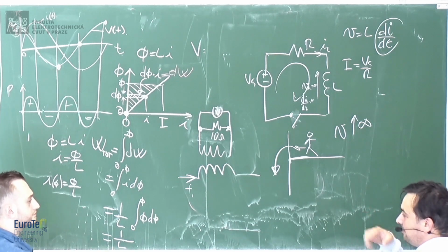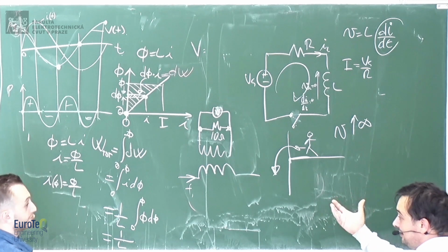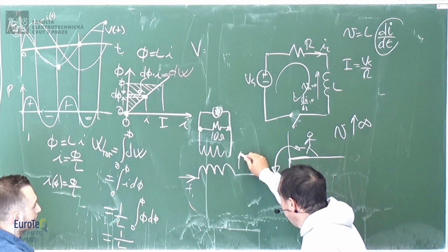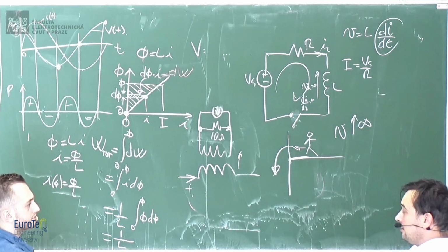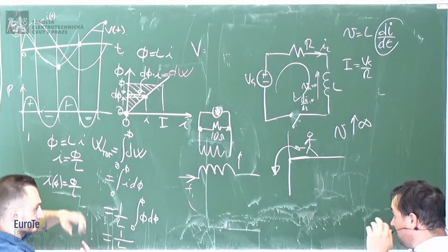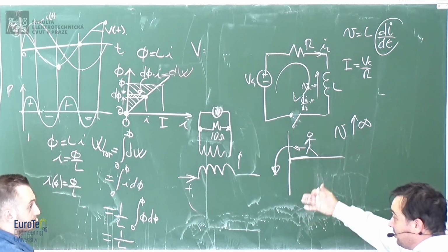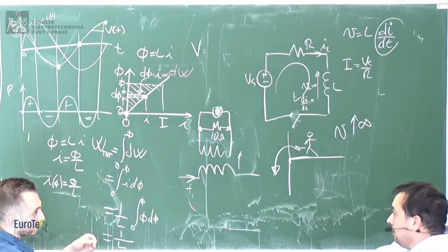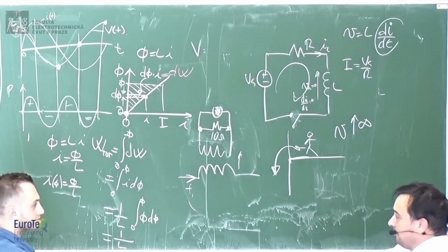From the practical point of view, but from the electrical point of view, it is still affecting because there is some energy which goes from here to here. Yeah, you add inductance to that wire. When you put the current clamp there, that wire has now more inductance because there's a transformer around. It's always a transformer, so it's taking some energy from the circuit. Mutual inductance, probably.